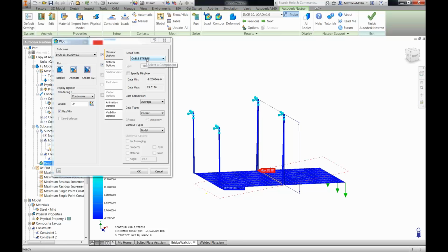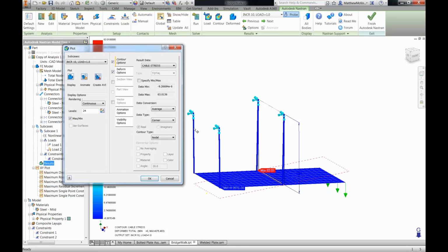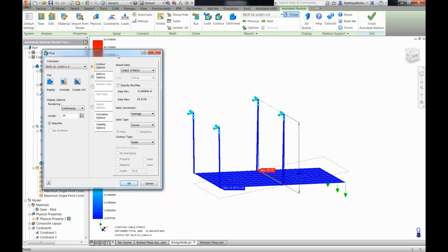So there's one thing to keep in mind, and it's the reason why I changed the rear of the part to have a cable, rather than a pinned restraint, so that we can actually see in this case that the cables work in one instance where we're under tension, but under compression, you need to look at understanding your structure. If that's a concern to you, understand your structure in a different way. But in this case, the cable is under no tensile load and is in compressive load, so there should be very little issue associated with that anyway.